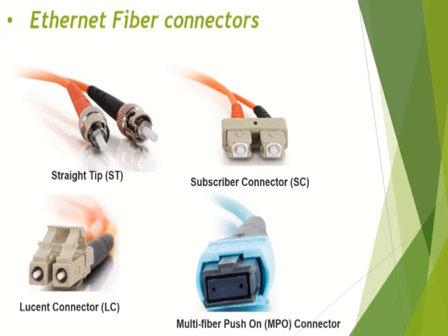Unlike the SC and ST connectors, the LC connector is always duplex, connecting a pair of fibers at a time. The fourth is the multi-fiber push-on MPO connector, another duplex connector that offers an easy option for connection. As the name suggests, it was designed to be connected multiple times without the creation of any potential connector issue. It is often also referred to as a fiber termination push-on.